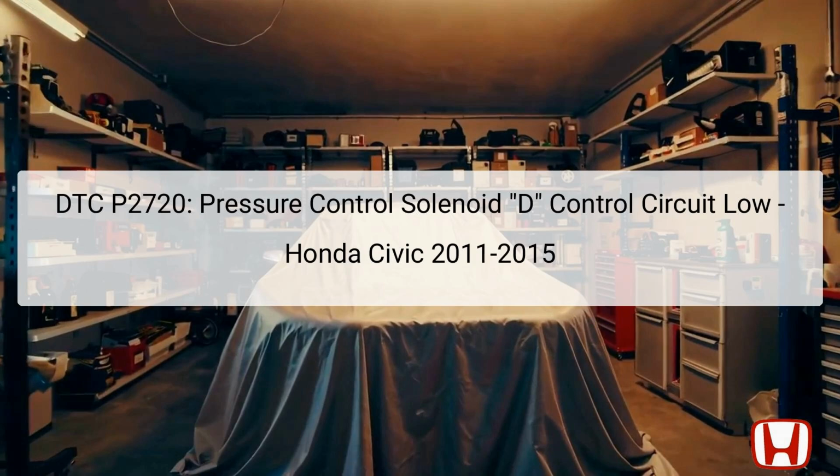The pressure control solenoid plays a pivotal role in regulating transmission fluid pressure, which in turn affects the shifting quality and overall performance of the continuously variable transmission, CVT. When a problem is detected with this solenoid's control circuit, it can lead to ineffective transmission operation. DTC P2720 typically manifests due to electrical failures, and understanding the circuit's layout and connections is essential for proper diagnosis